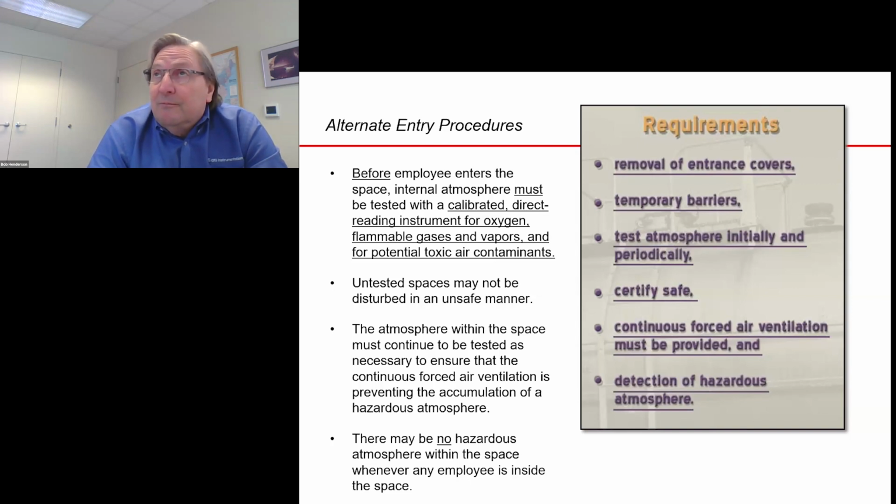If the owner's manual says that you need to test the instrument or calibrate the instrument on a daily basis, that's your obligation. For calibration, the calibration frequency and circumstances which merit a calibration adjustment to be made are up to the manufacturer of the device.